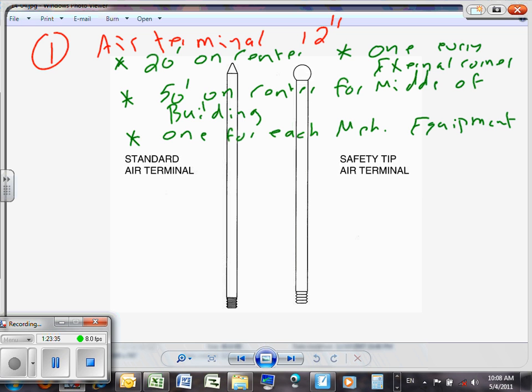That's easy. And then annotate, guys, detailed line, have a dotted line or some type of a line that sticks out, and connect all of them together in a loop. And all these spikes for the mechanical equipment, take a loop also, annotate, and connect it to the main loop. So that's basically what we're going to do for the lightning. Okay, so that's number one.